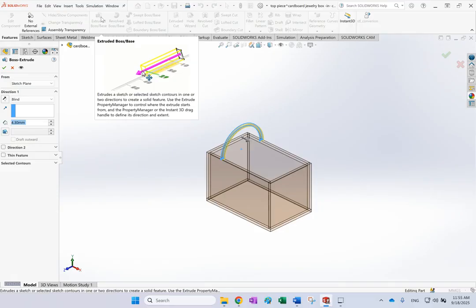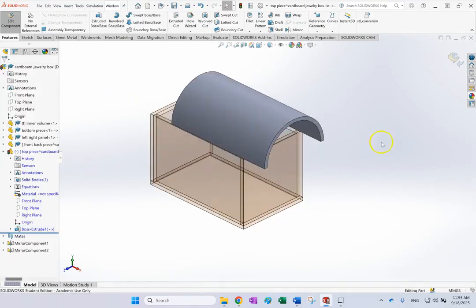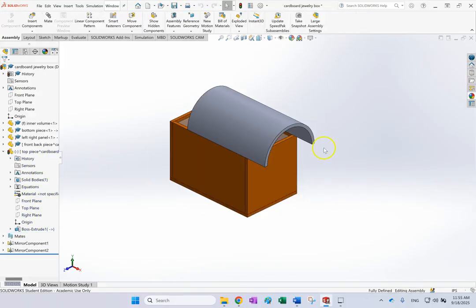So this is the place that you need T, not for the sketch, but for the extrusion. So here you say T times 2, this is for the two cardboards on the left and right, and then plus 130 mil. Okay, so now this should be exactly the right size, and I'm gonna show you why.